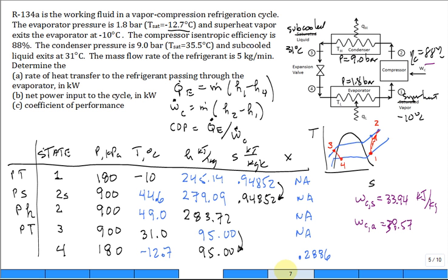That's not going to provide the cooling. The 70% that's by mass that's still in the liquid state provides the cooling. That's what evaporates in the evaporator. Okay, so that's state 4 was fixed by knowing the pressure and the enthalpy. Well, you take the difference in the H1 and H4 multiplied by m dot, and let me just kind of tuck the solutions in somewhere without having to mess up my page.